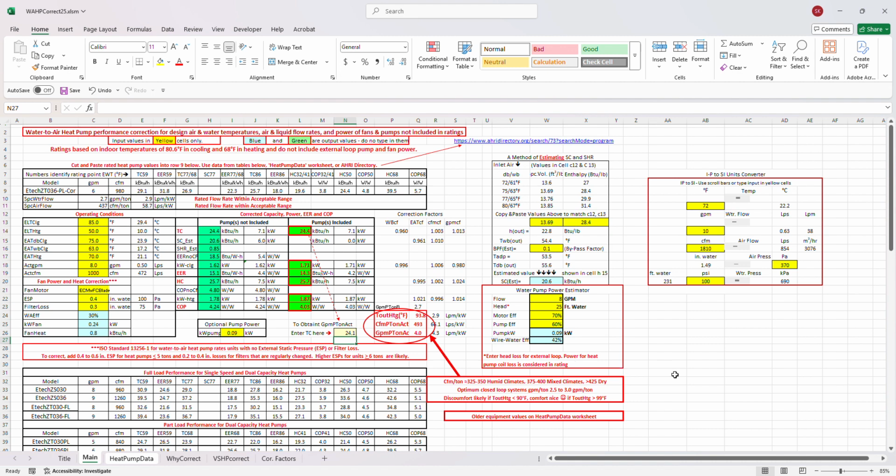So anyway, you can see that our CFM was high, so our temperature blowing on people in the rooms is 94, and then the sensible heat ratio is not any good. It's 85. We're not getting much dehumidification. So let's try dropping this down to, let's just go to 750, okay? See what happens. Yeah, that did good.